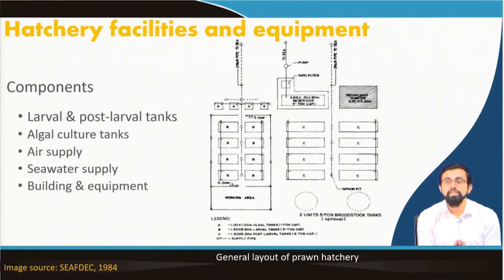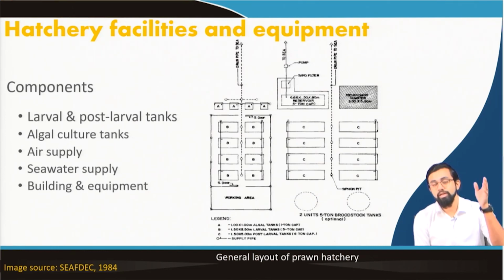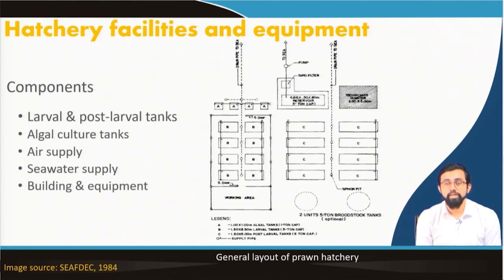But suppose this electrical line is far away. Design is very important in each and every aspect: where the electrical connections will be, what type of aerators have to be provided. The aeration efficiency will reduce if you have a central aerator line, from where you are supplying the aeration through a conduit system to different tanks. The farther the tank is, the lower the efficiency of the aeration unit will be. So just to give you an example of why these small things matter.